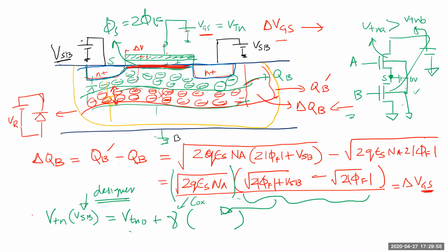So the line of thought is, if I applied this surface potential, this much charge will form in the channel area. But once that forms, it will actually change this surface potential, because now your depletion looks like this with the same gate voltage, which means that this phi s probably increased or decreased or whatever happened, right?